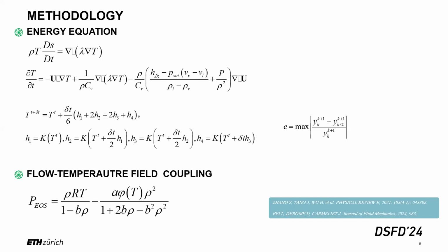Yeah, so I think you made the comment that the role of hysteresis is quite small. But I think this is because of the geometry that you've chosen, the motion of the interface is only in one direction. So I think it's probably not critical. But I can imagine that if you have a geometry that is a bit more random, you might get a phenomenon like Haines jump, and then you will actually have the interface advancing and receding at different times. Then maybe you will actually see that hysteresis is important. So I wonder if you look at that sort of geometry that's more complex and less regular.